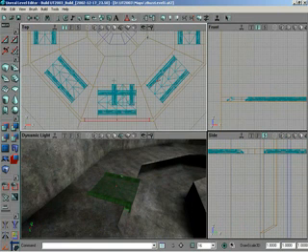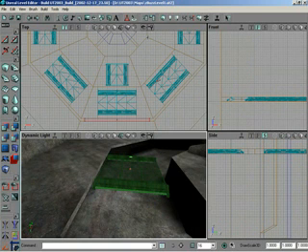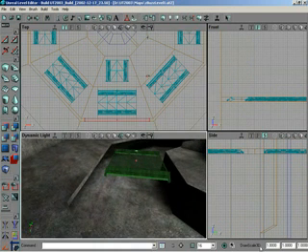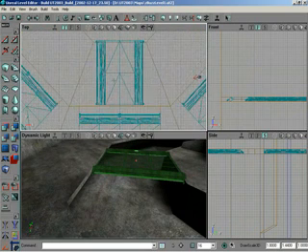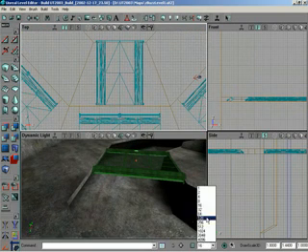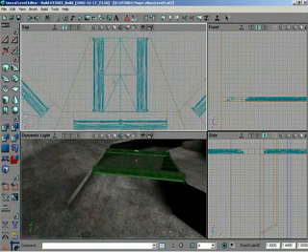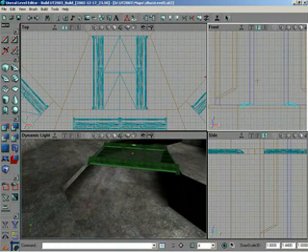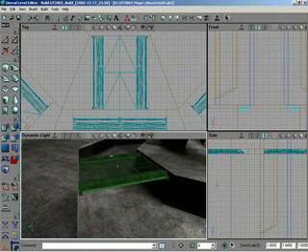So let me go down, and I'll drag it to the center. But you see that it doesn't quite fit. And if you added 2, that would be too many. So what I'm going to have to do is scale it out just a little bit. Under Draw Scale 3D, I'll grab the second axis and set it from 1 to 1.44. Very nice. I might have to drop my grid a little to get that snap just right. Let me try 4. Zoom in here, and that's very close. That should be right about there. Let me zoom in from a front view just to check the height. Move it down just a little bit. And there, now I've actually got the walkway across, and it fits.